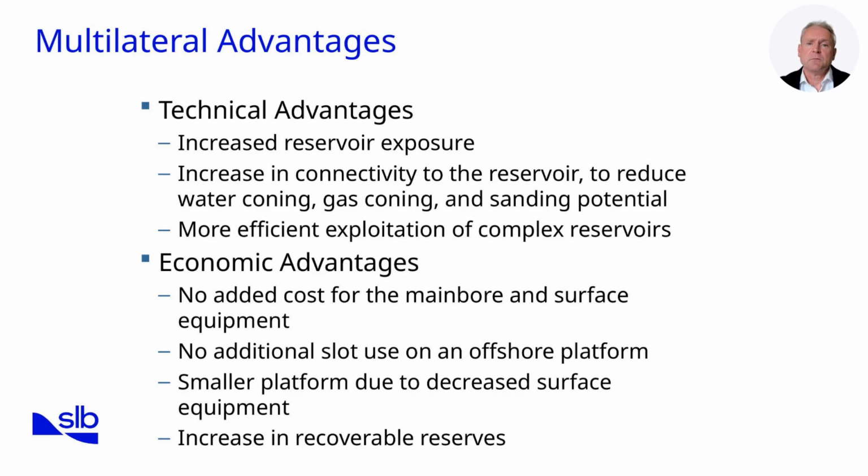Multilaterals also allow more efficient exploitation of complex reservoirs, particularly where thin, compartmentalized or fractured zones would be uneconomic to reach with multiple conventional wells. On the economic side, we avoid duplicating the cost of a second surface well bore. The same surface facilities, wellhead, casing, and infrastructure serve all laterals.